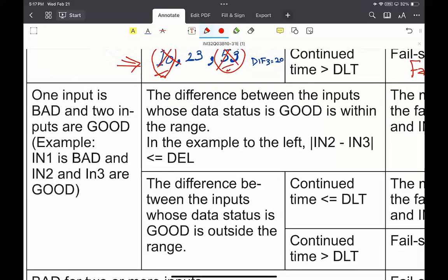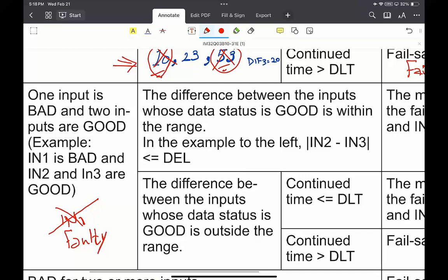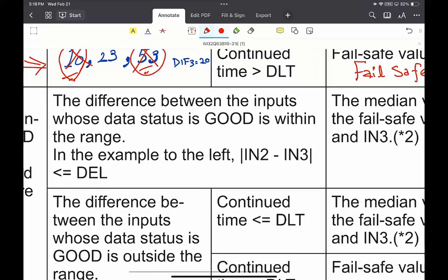So in the next part, we check the quality of the transmitters, and here we have one missing signal, input 1. The transmitter is faulty. Possibly the transmitter is dead or out of range. So this system reported via a quality signal that input 1 is not good. So we don't have input 1, so we check the input 2 and 3, the remaining good quality signals. And as an example, consider we have input 1 that is not important for us, but still we have 22, 23, and 25.